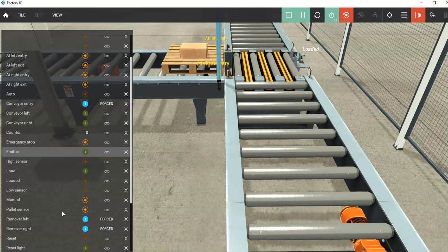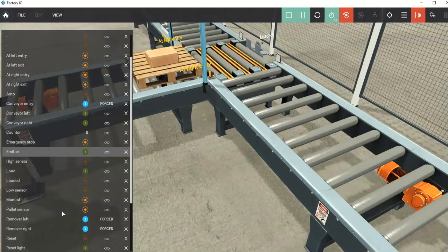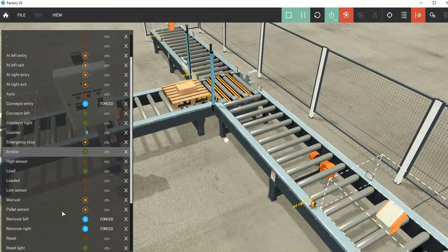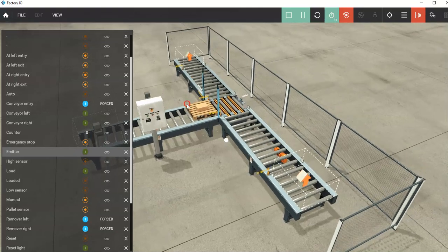So what happens here is you're going to see the pallet go first, then you're going to see the box up here, then the box goes away, so the sensor will go high, and then when it passes it'll go low, which means you're going to have to latch the box height, and then the pallet goes away. So that's kind of what's going on there. And also, I'm not very good at it, but you should try to practice and get some pretty good views.